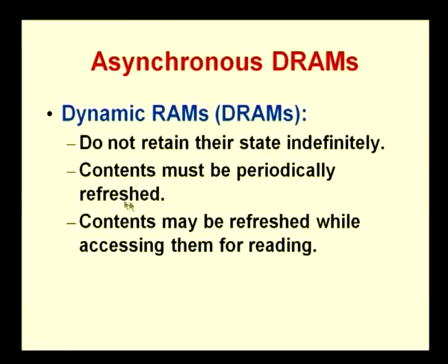Now, with a dynamic RAM, you cannot even do that. If you store some data, after some time the data is likely to be lost even though the power is applied. Which means we will have to keep on refreshing that content periodically. Because it does not retain the state indefinitely, we have to periodically refresh the contents which are stored.